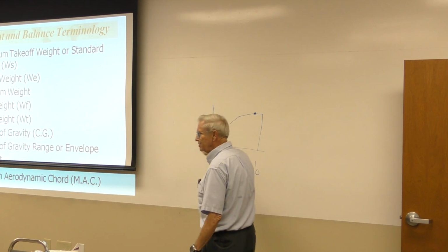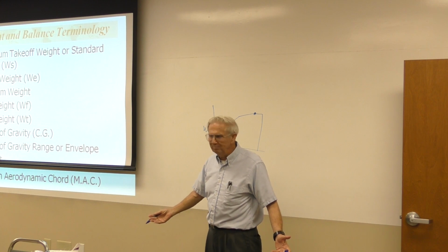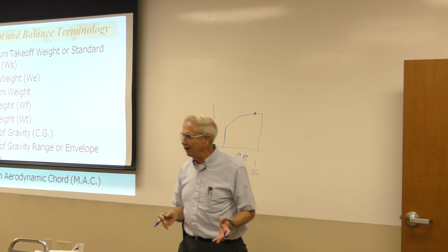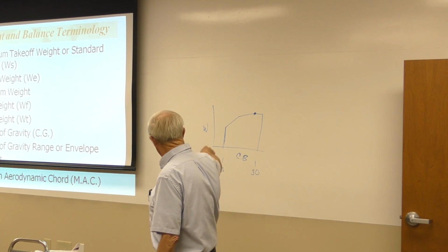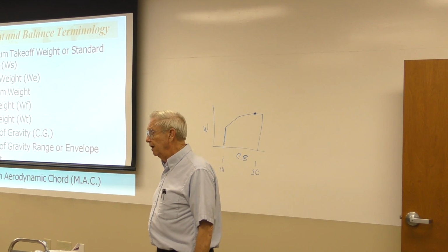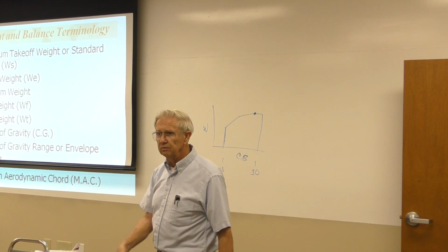Inches after datum, since the datums on these airplanes are all in different places, doesn't have much meaning if I'm trying to compare airplanes, does it? However, mean aerodynamic chord does, and I can compare a Cessna to a Piper to a whatever.